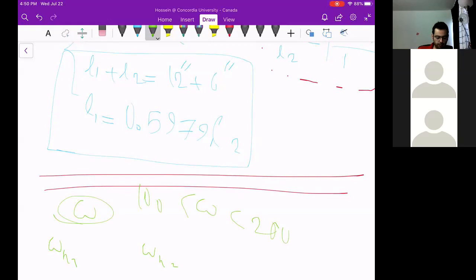And once you turn off the system, there is no choice. There is a huge vibration because one of the natural frequencies is 0. But for omega n2, you have to be far away from it. For example, if omega n2 is 95, you cannot apply the external force close to that.